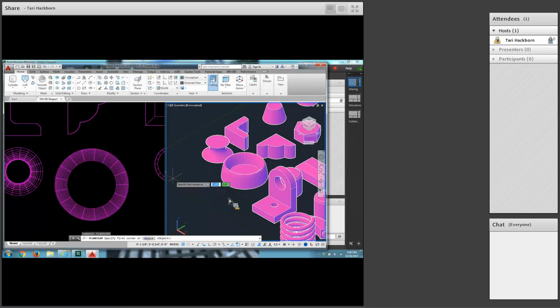So pick a location here in front of the lofts, and then type @3,1/2, and enter. And it makes it pretty long, doesn't it? It might start in a spot where I have to end up moving it when it's done. Okay. Then type thicken.